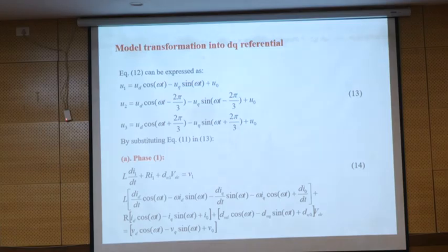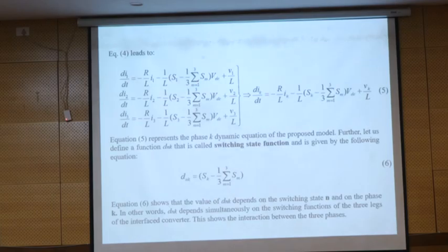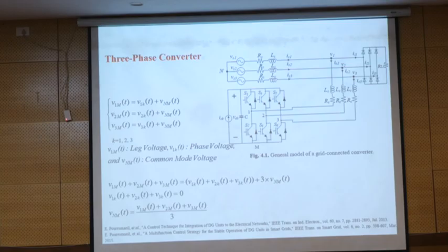I mean, this is the switching in leg 1, leg 2, leg 3, okay? So when we say S1, it doesn't mean this one, okay? It is this one or this one. It's leg 1, okay? So one of them can be on, one of them can be off, and based on that you can have the actual output voltage. It can be either 0 or VDC. We will take either 0 or 1 VDC, in that case. In the next slide.